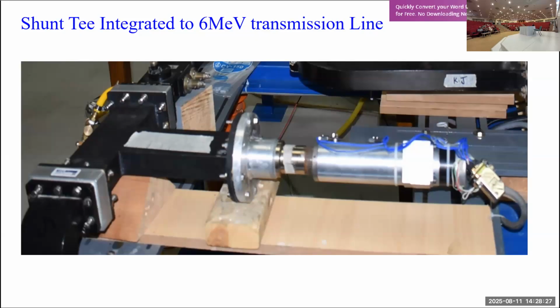You must know the temperature of water coming in, the temperature of water going out, the heat capacity of water, and how much volume of water passes through this cooling channel every second. And you can reasonably estimate the power delivered to the electron beam or particles being accelerated.